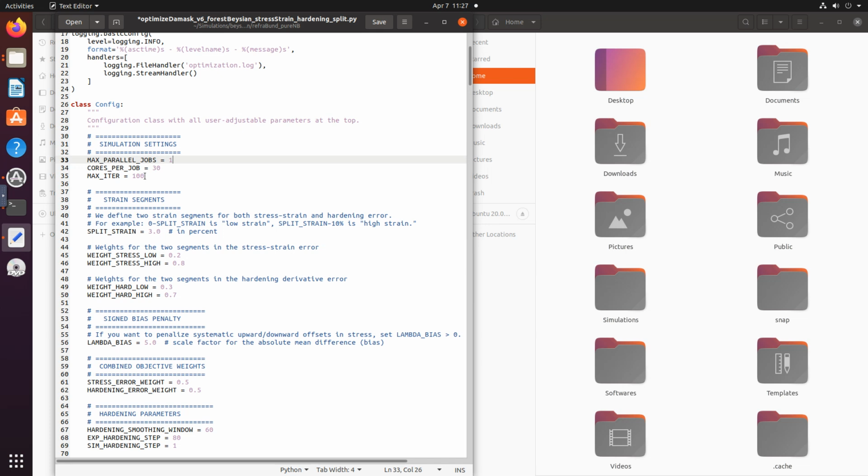See how much different it is, how much there is a difference. Then based on that, it will change its material parameters and then we'll run a simulation again. So the first was one iteration, the next one is the next iteration. The more iterations it will do, the closer it will come to the parameters, right? But we do not want it to run until infinity. So therefore we, for example, can define 20, 30, 50, whatever, right? So what I will do here for this example is I will restrict it to 10.